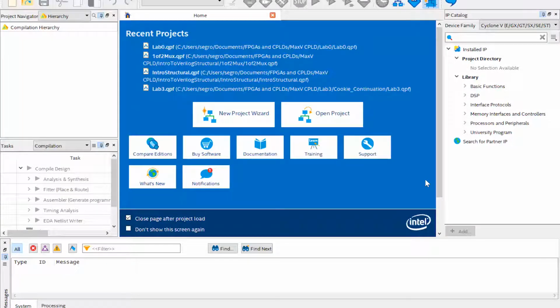There's really no point. It's not 5 volt tolerant inputs, so there's really no reason to have 5 volts into it. The only reason I put it on there is I thought the people might be used to 5 volts and they would step it down, but it's just more potential to cause problems.